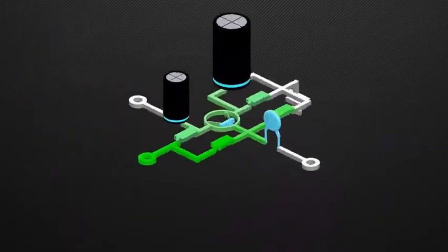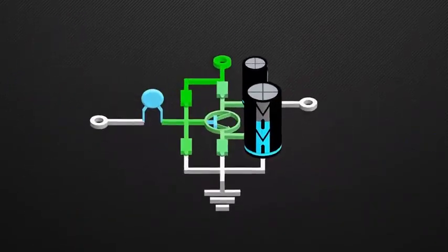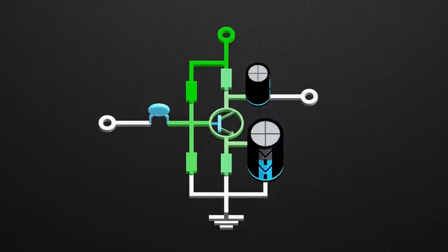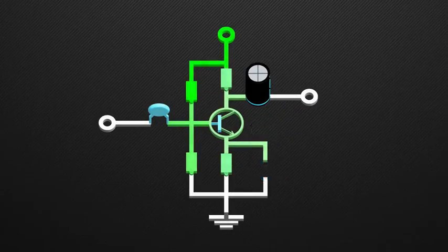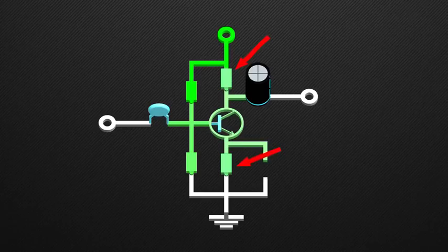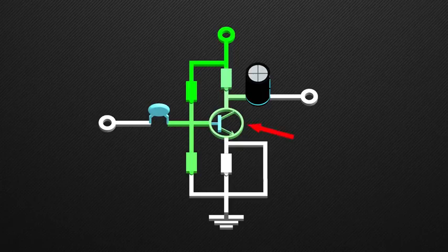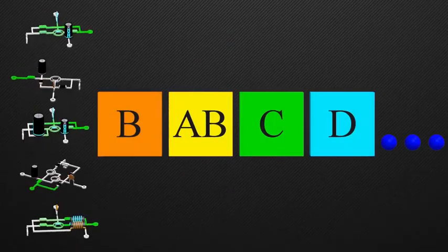This circuit has a capacitor across this resistor. This increases the AC gain of the amplifier. The capacitor will block the DC, thus the amplification of DC will depend on the resistors, but for AC, the capacitor will act as a short circuit. Its gain will depend on the beta of the transistor, which is in hundreds, thus you can amplify a very weak signal to a strong signal.